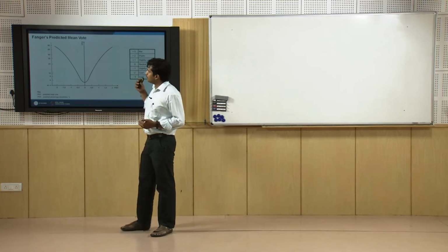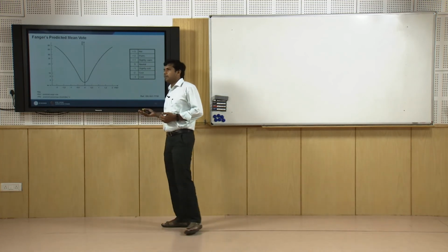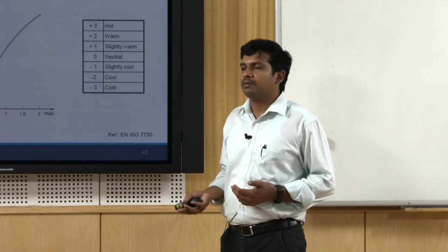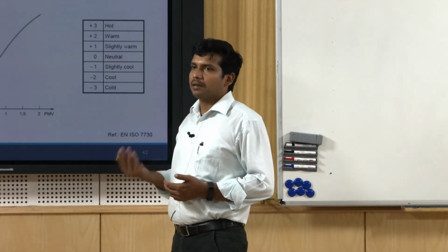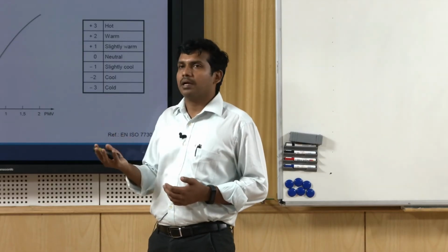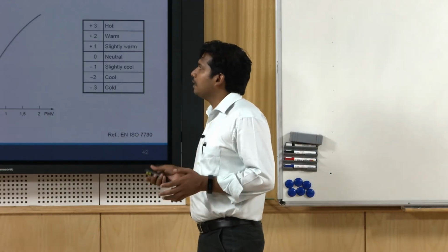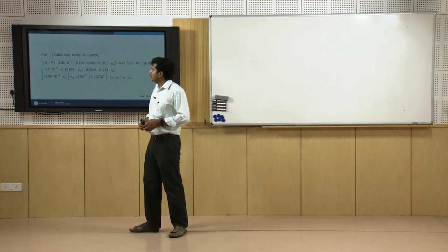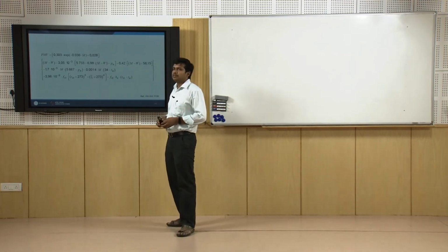So there is a lot of debate about whether Fanger's PMV model really applies to the field. A lot of investigations say that it needs a correction before it can apply to the field. Some authors also cite that this is far beyond field application, more of a lab oriented index. But all said and done, this is a parametric, or rather empirical, equation on which the PMV is derived.